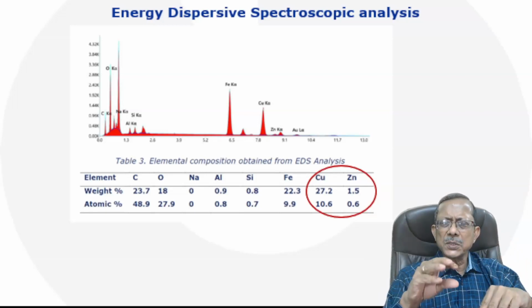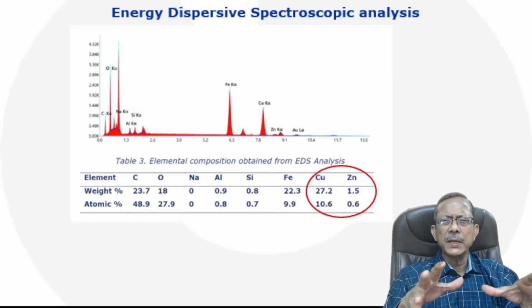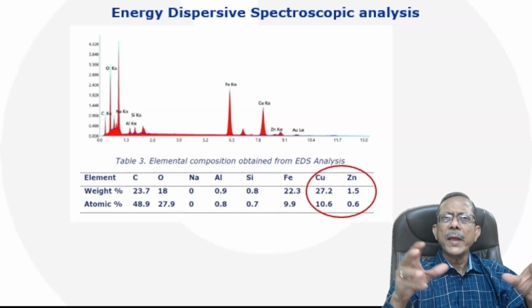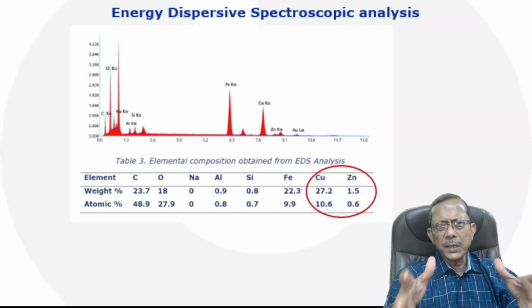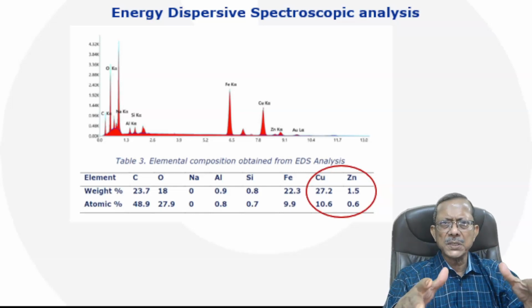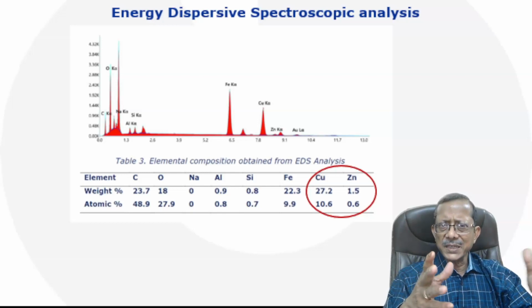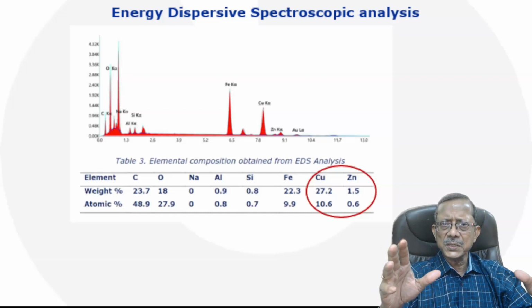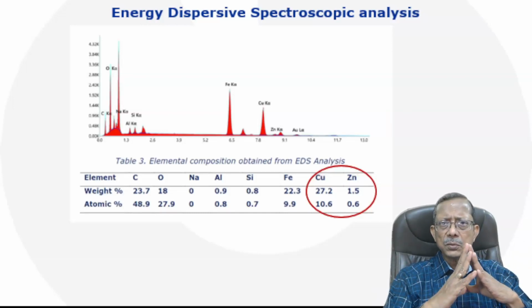And if there are deposits of these conductive metals, it is definitely going to create a very strong galvanic cell in the system where corrosion will definitely occur. And wherever corrosion occurs, there will be deposits, then there is a chance of under deposit corrosion. We have already seen the film boiling indications. So below the film boiling, corrosions can occur. There is no doubt about it.